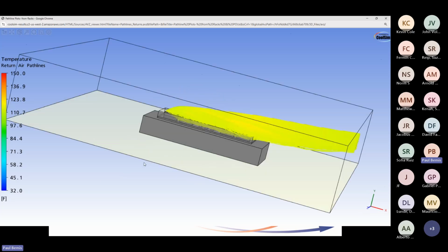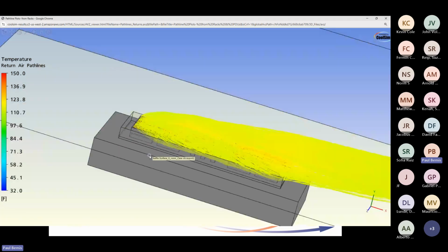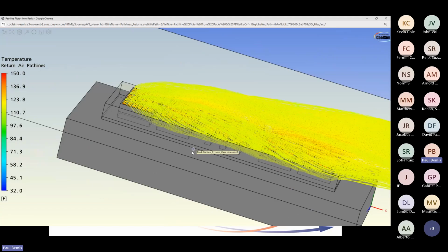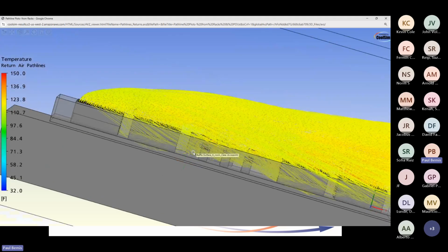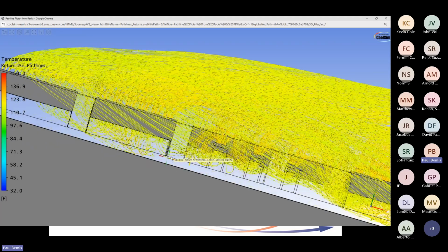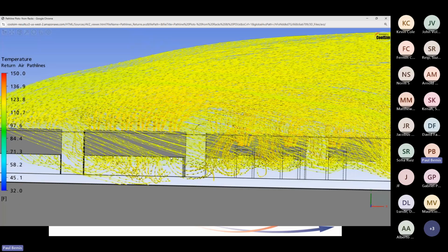So with your mouse, if you want to follow along, you can see here what's going on with this design. I've got wind now blowing directly from the left to the right in this image, and you can see that I've got recirculation going on. Now, one of the nice things about this viewer is if you're not on a Mac, you've got a right mouse, you can hide a surface. So right mouse, hide. So I just hid the surrounding screen, and using my arrow keys and my control key to manipulate this image so that you can see the recirculation.